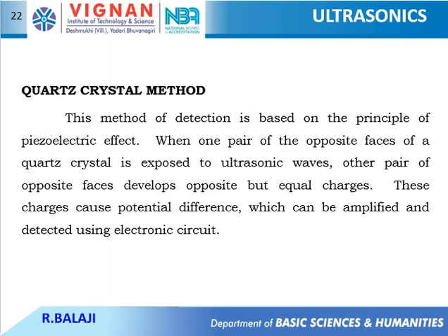And the last method is the quartz crystal method. This method of detection is based on the principle of the piezoelectric effect. When one pair of opposite faces of a quartz crystal is exposed to ultrasonic waves, the other pair of opposite faces develop opposite but equal charges. These charges cause a potential difference, which can be amplified and detected using an electronic circuit.